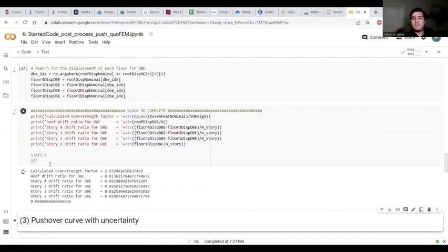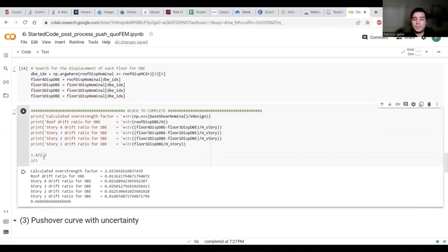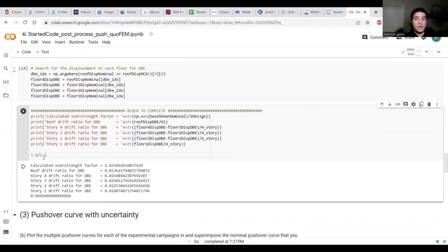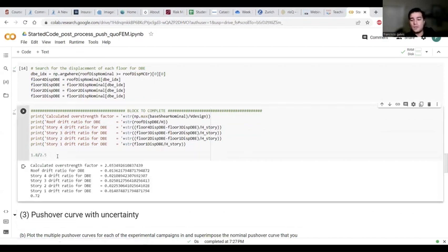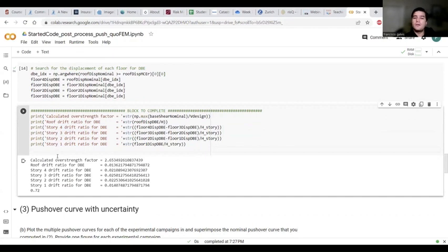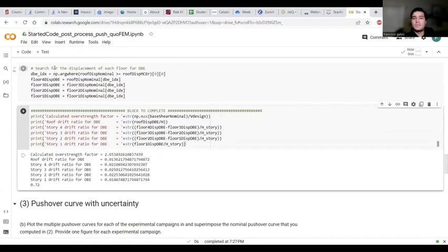We take the MCE aspect and reduce it, multiply it by 2/3, but looking at the ratio of drifts, it is not 2/3. The ratio of drifts is bigger, it is 0.72, which speaks again to the nonlinear behavior that we see in this structure and in any structure really.